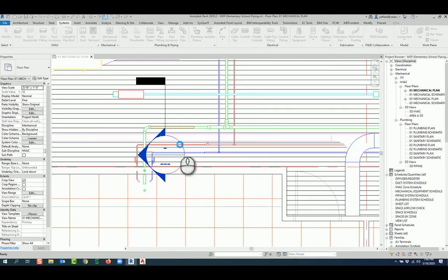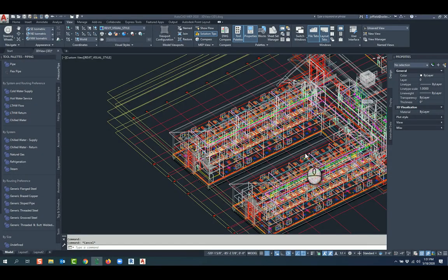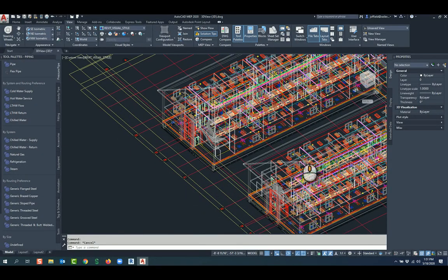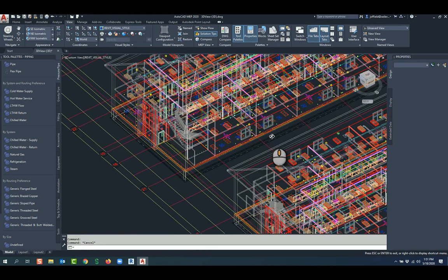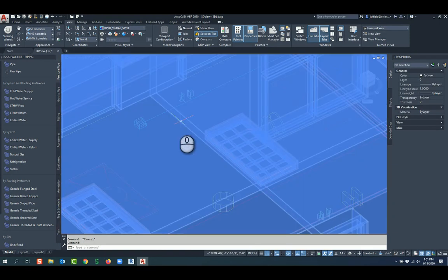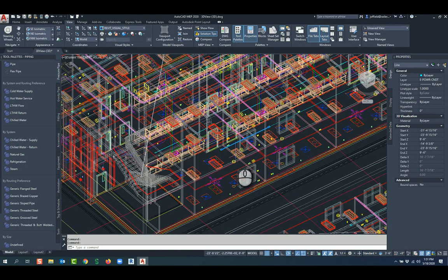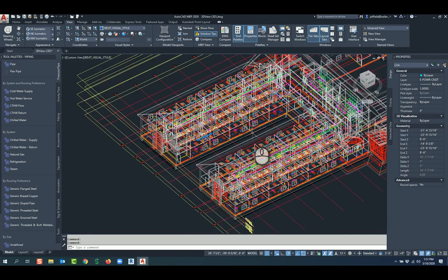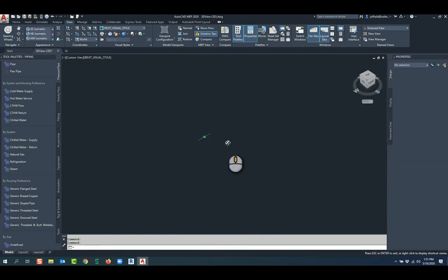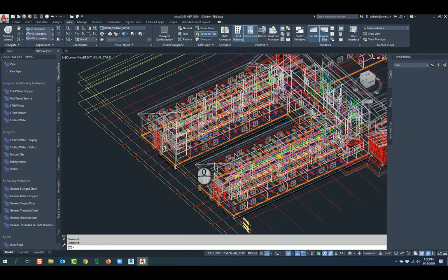And if you don't have your shape parameter set up, it'll give you that little warning there. As you can see in the bottom left, we actually have that file being exported out and processed. And we'll be able to see this AutoCAD file here shortly within our AutoCAD. So now we have that same file here in our AutoCAD MEP, and as we zoom in, we can actually see it. We have those components with the layers, and all the information then comes through, even as a 3D file here that we see within our CAD format from Revit.